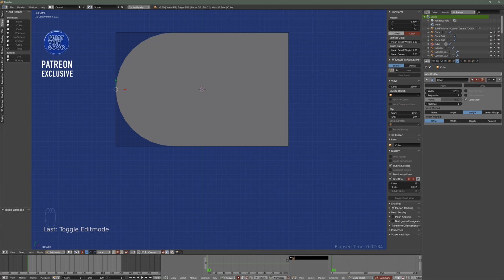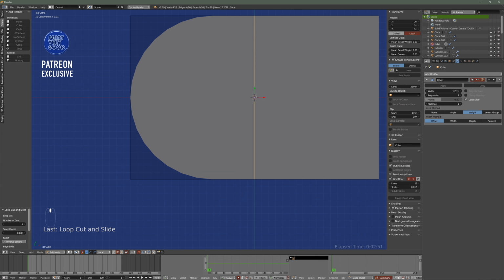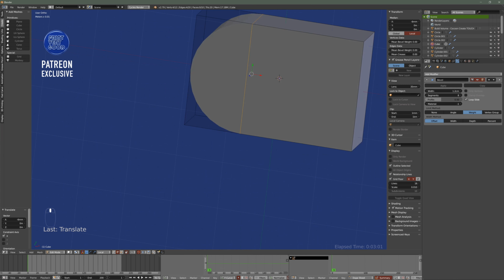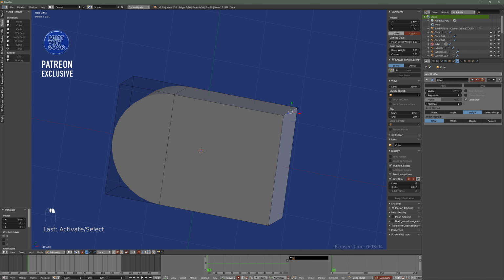Now what I might also do is put a cut across this object while I'm here, just a loop cut, and I'll switch my snapping tool to increment. I'll come down here, I'm going to move it on the x-axis to this point here, which will be 12 millimeters in from the edge. So now that I've done that, I can delete this edge,